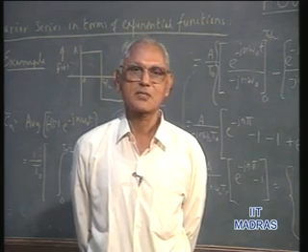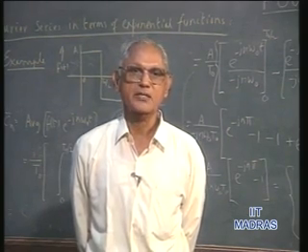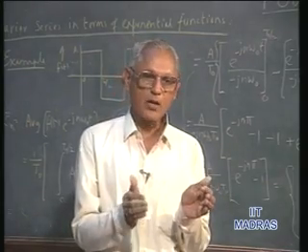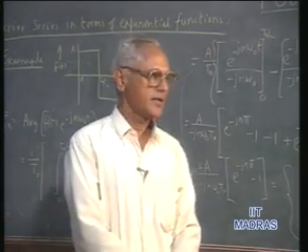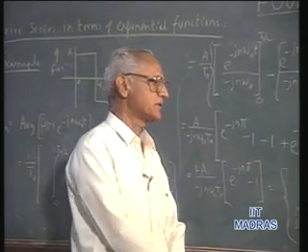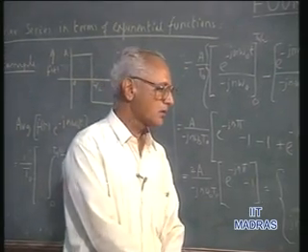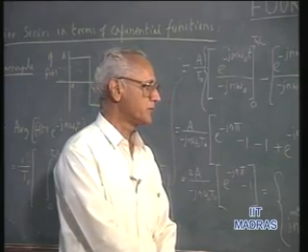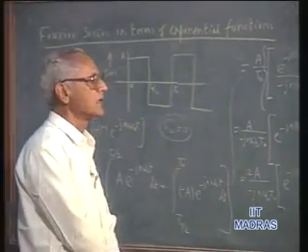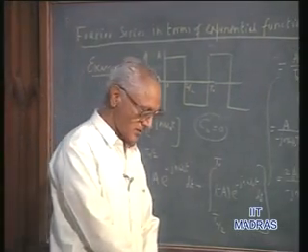The even part was a full wave rectified sine wave, where whatever waveform is there in one half cycle is reproduced, and therefore we have only the even harmonics present. We found out the Fourier series expansion of the even part and odd part separately, and used such a kind of waveform